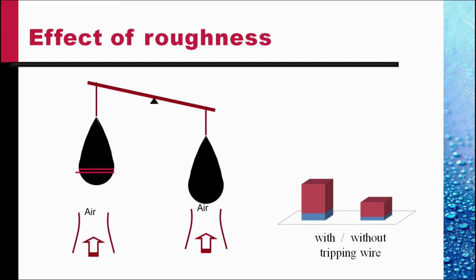the drag on the rough streamlined body is much more than the drag on a laminar streamlined body. That's why attempts are made to keep the flow on aircraft wings, which are streamlined, to be laminar as far as possible. The whole class of aerofoils known as laminar flow aerofoils have been developed for the purpose.